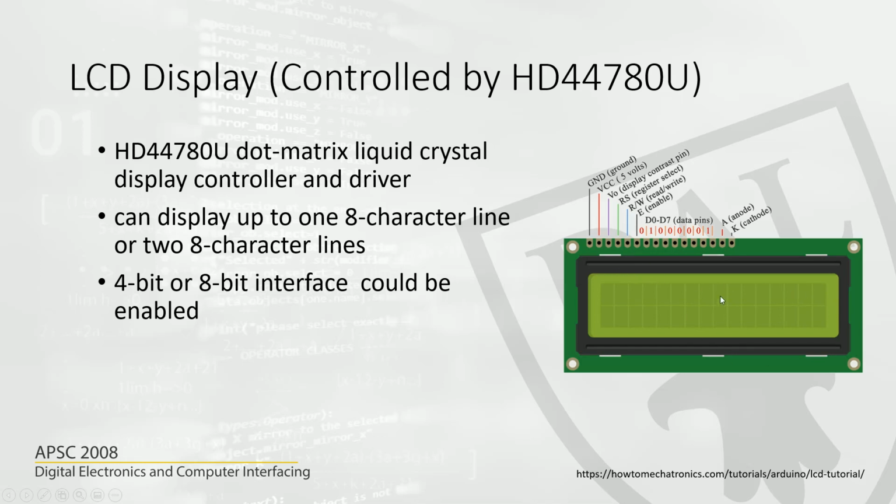Don't put your hand behind the LCD display, as that might burn your fingers. I don't want that happening. So again, here we have a ground, we have 5 volts, and we will be using a variable resistor so that we can change the contrast of this pin.